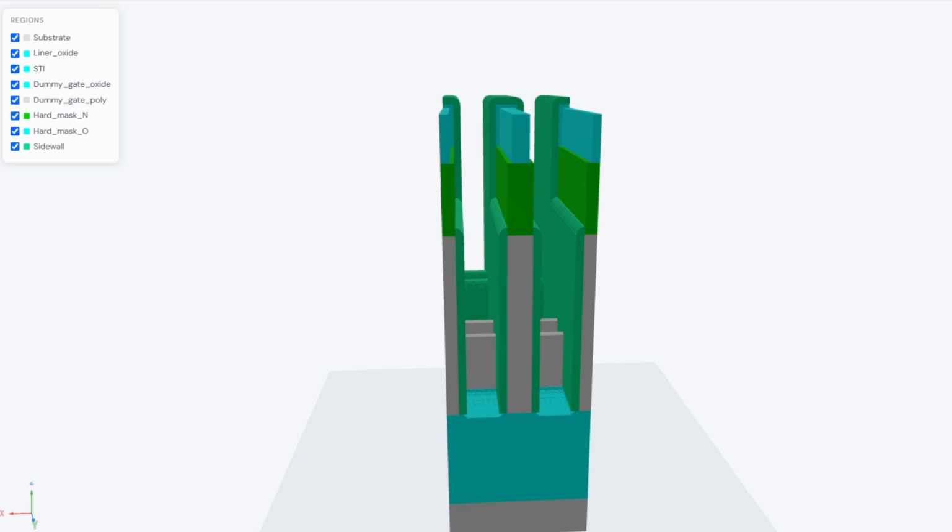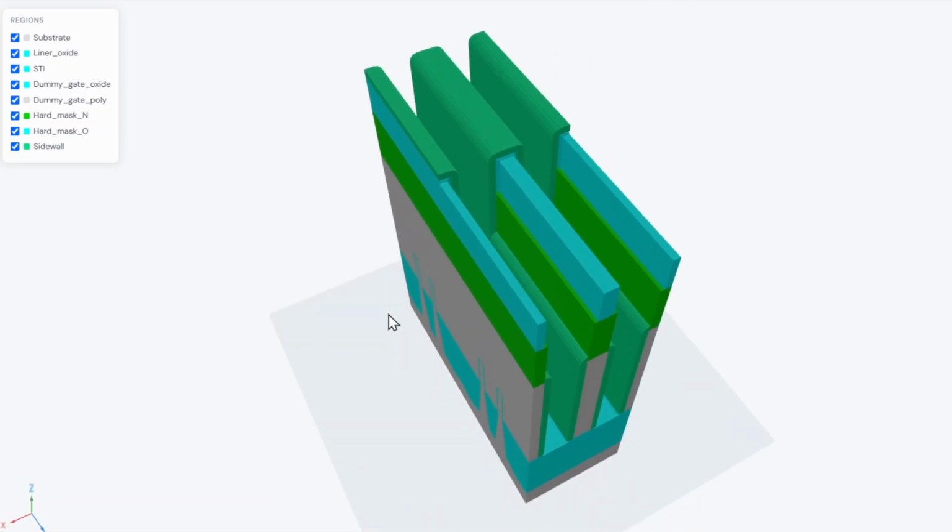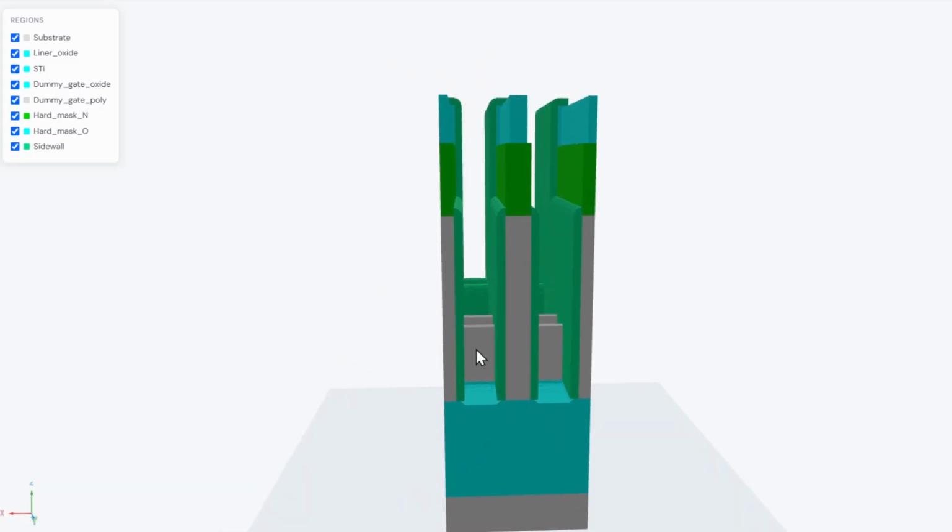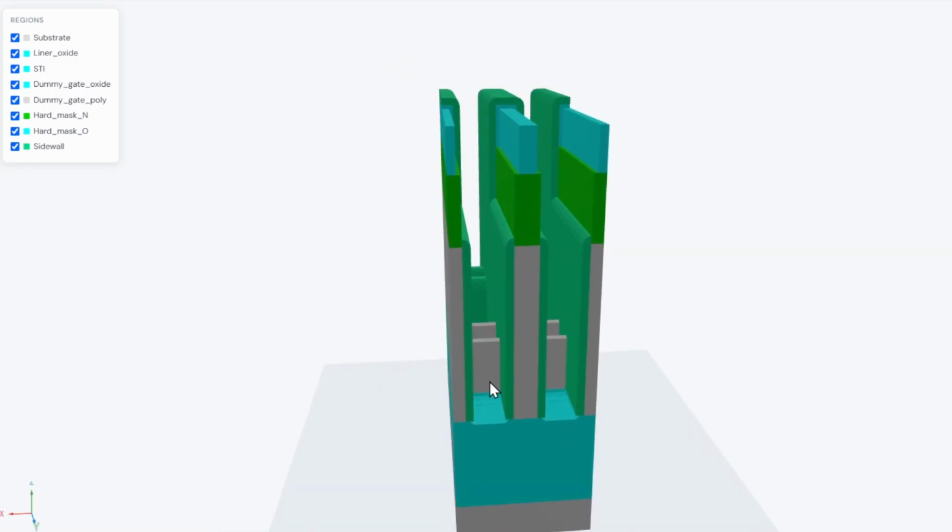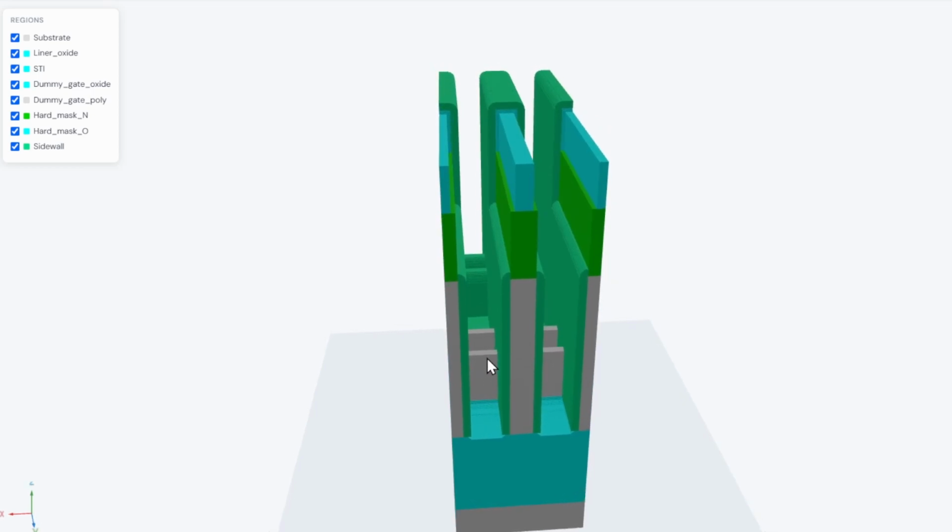Now we have the case for a P MOSFET, and we have to grow the P MOSFET source and drain, but we still have the fin itself. Usually, in order to maximize the impact of silicon germanium source and drain, we intentionally etch this existing fin. So let's do it.